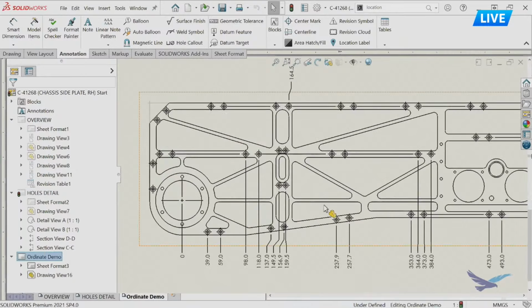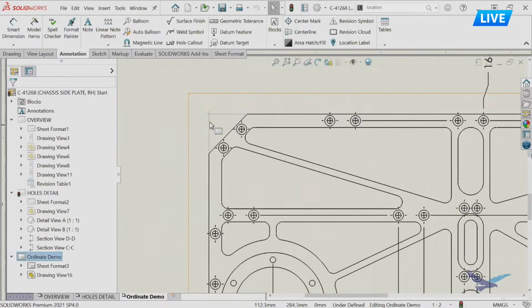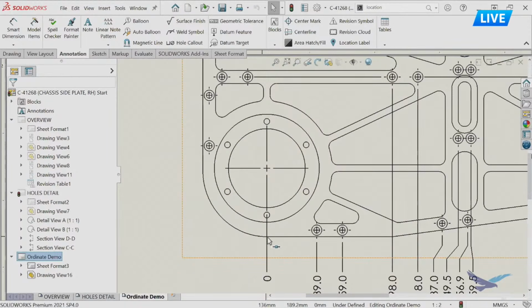And the last topic I wanted to cover before we switch off to Tim is virtual sharp creation. So you can see I have an imaginary sharp corner here at the intersection of these two lines. And this is another challenge that you may need to do, get some kind of representation of a virtual sharp there for clarity. And there's 2 ways to do it.